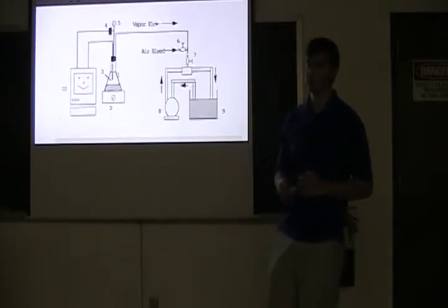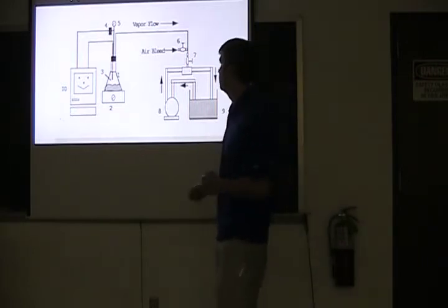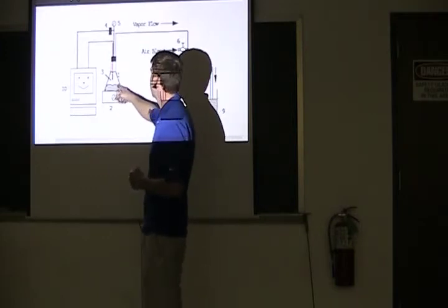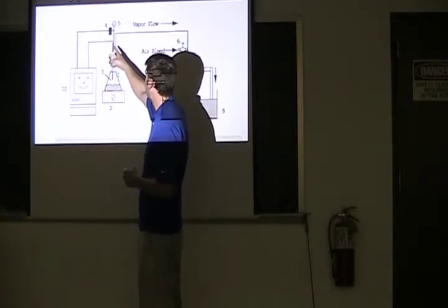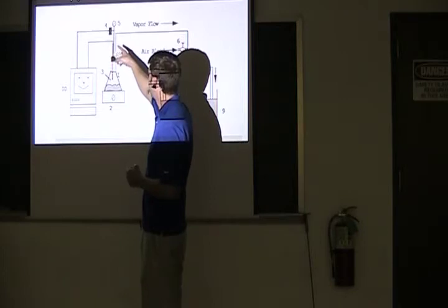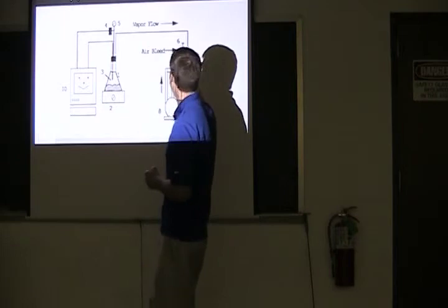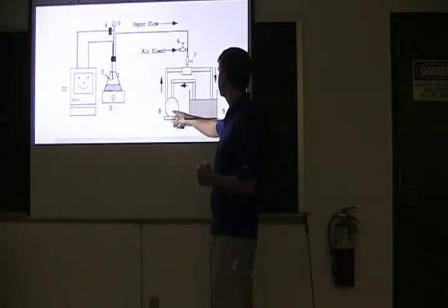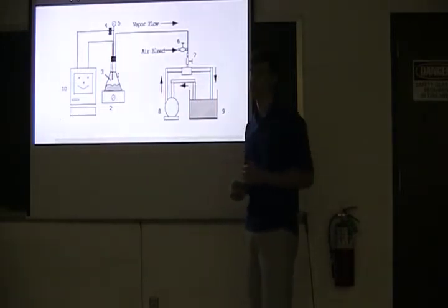The apparatus that we'll use for this experiment is exemplified by this schematic. You have the beaker, and you have a heating plate, which is going to boil the water inside the beaker. You have the thermocouple, which is going to be taking the readings, the analog pressure transducer, the analog readout gauge for pressure, an air bleed valve, the vacuum control valve, the centrifugal pump, a water reservoir, and a computer that runs the data acquisition software.